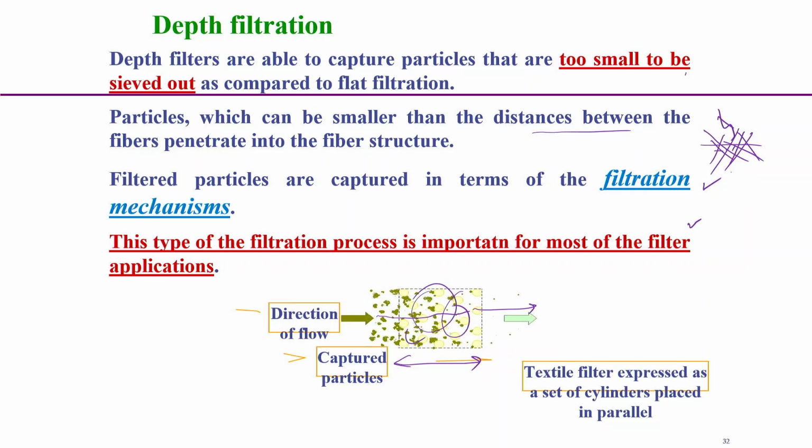So, we should keep the pore size larger, so that air can flow through easily, but at the same time we should design our filter media so that particles are captured within the thickness of the filter media.